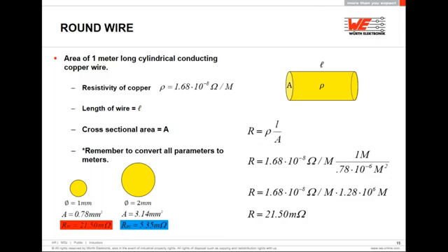With this example, it is shown that the bigger the diameter, the bigger the cross-sectional area. Therefore, the direct current resistance would be smaller. Of course, you could adjust any of these variables in order to get different DCR values. This formula is quite helpful for this.